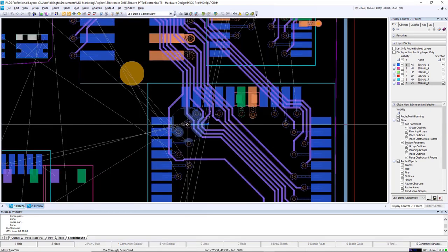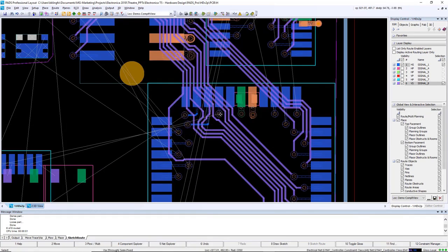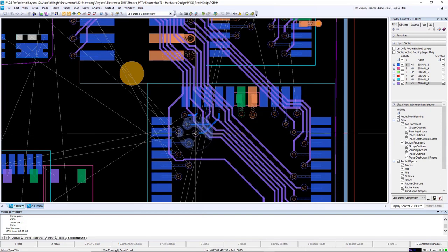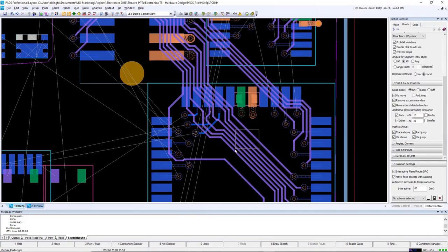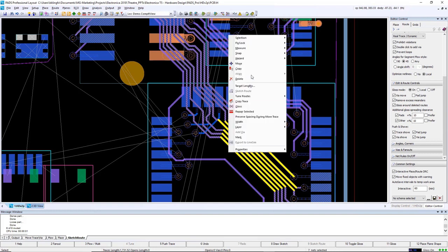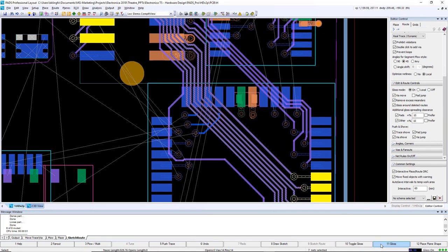With the third group, we can see that it's interlacing between some vias, which I know I can fix by moving the vias. So again, using interactive route technology in Professional, I can very quickly move these vias and do cleanup on those nets with very little manual interaction.